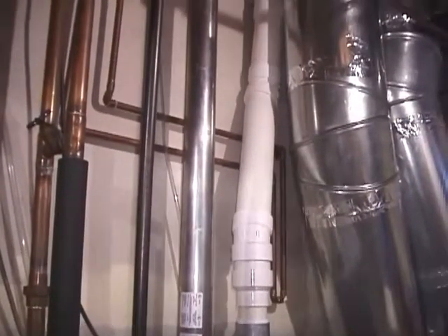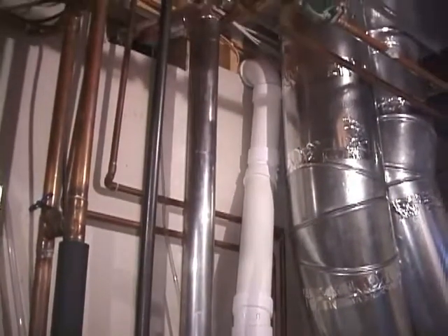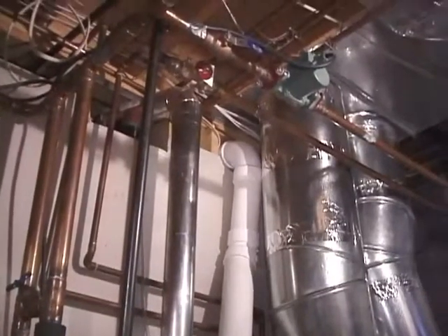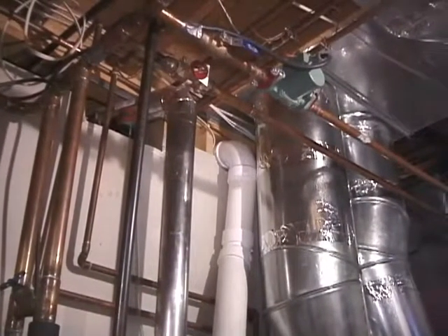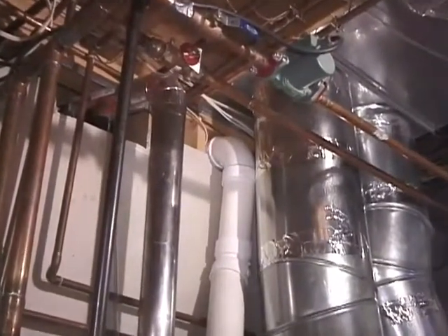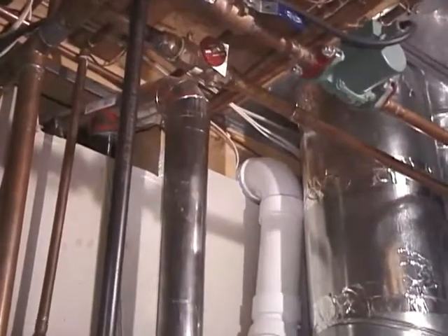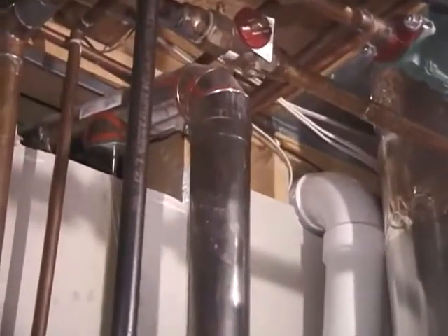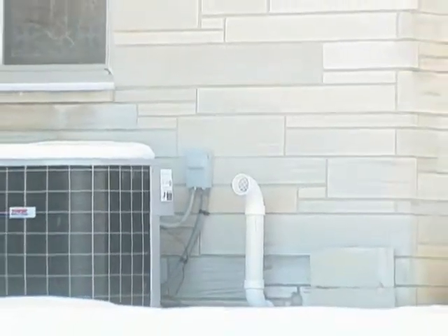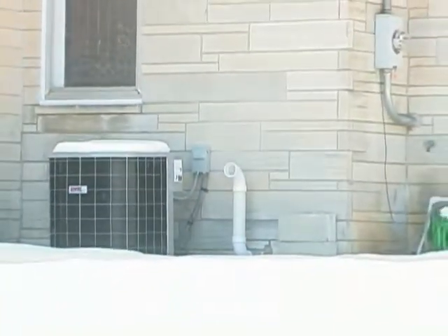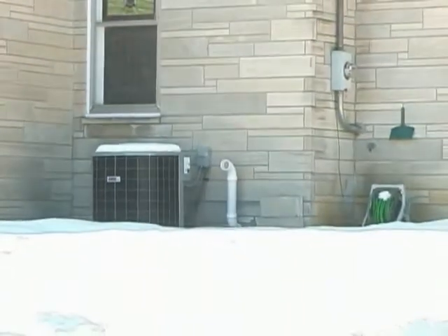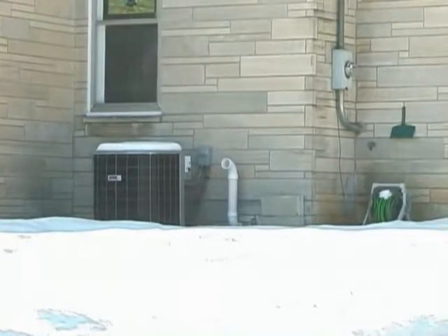Because the vent connected to Category 3 appliances, as well as Category 1 appliances that are converted to Category 3, operate at a positive pressure, they require an airtight vent system to avoid leakage of flue products into the building. Remember that plastic is no longer allowed for use on Category 3 appliances. An exception would be the power shot type of water heaters mentioned earlier.